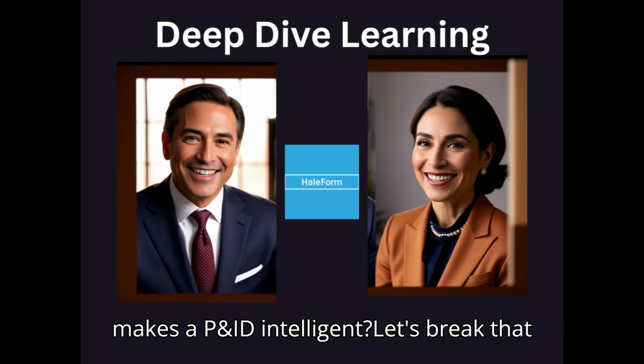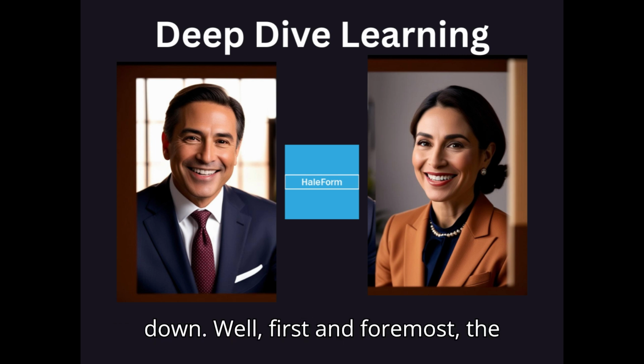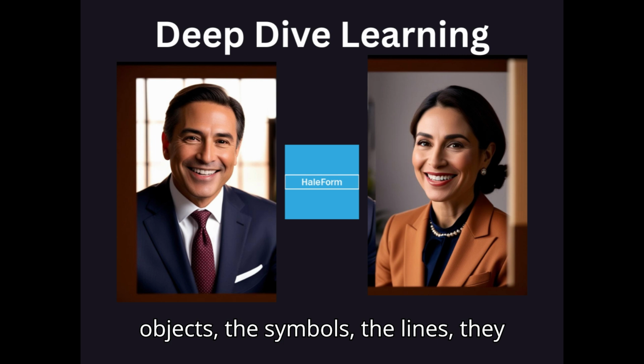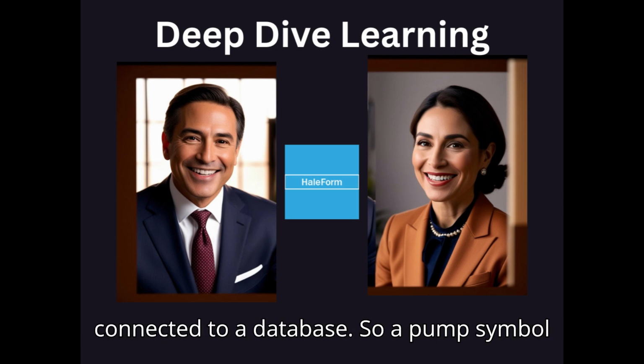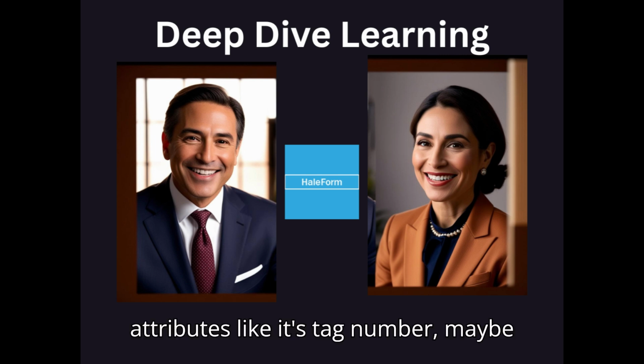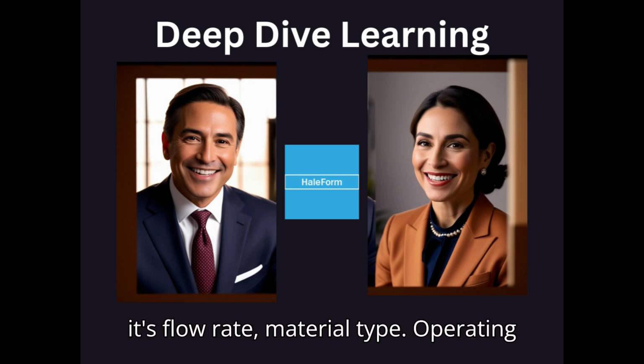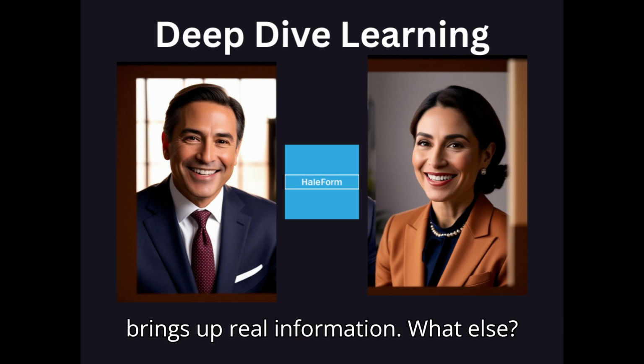So what actually makes a P&ID intelligent? Let's break that down. Well, first and foremost, the objects, the symbols, the lines, they have data linked to them. They're connected to a database. So a pump symbol isn't just a picture. It's linked to attributes like its tag number, maybe its flow rate, material type, operating pressure. Okay, so clicking on it actually brings up real information.